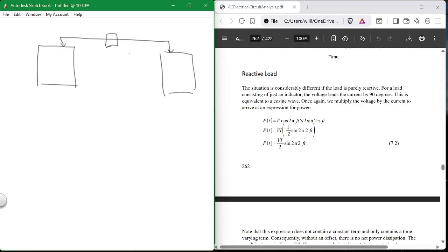There's pull boxes, okay? Now the rule in most people's mind is you do not go into a pull box and junction and start building circuitry out of a pull box, because one end of that wire is here, the other end of that wire is here, and you don't take a wire in here and cut it and then do something else with it and then do something else. You don't do that, okay? And they were constantly. Well, we need some 110. We'll go in and take a little circuit with 110 and we'll go do something with it over here. Why is that not proper?